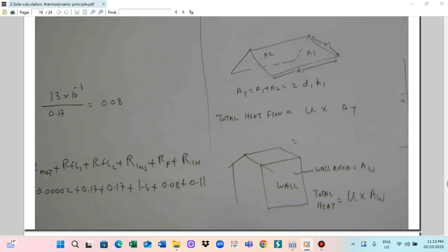Those heat flows are the important factor. All the heat has resistance, heat resistance. Heat resistance value, their arrangement, their construction, we take into account. So now in these two problems, we show how to take the heat resistance value, how to arrange it, how to see the table. So like I said, you can calculate total U. After you get the U, you multiply it by the area and you can calculate the total heat flow. And then you will be able to calculate the air conditioner size.